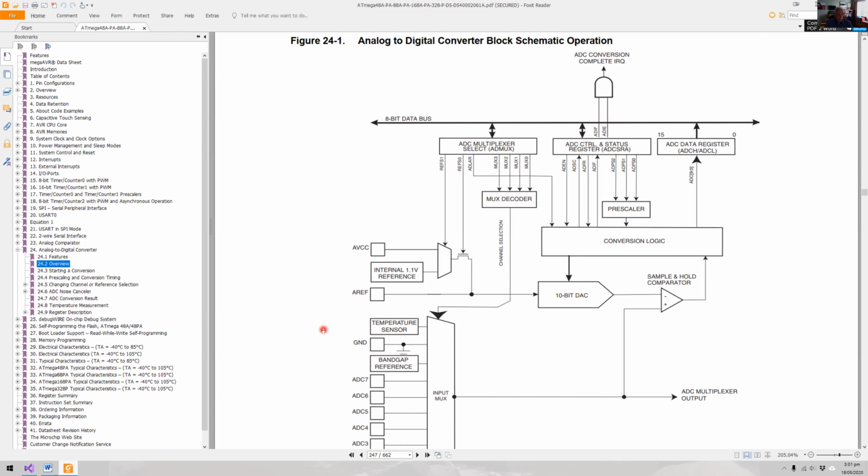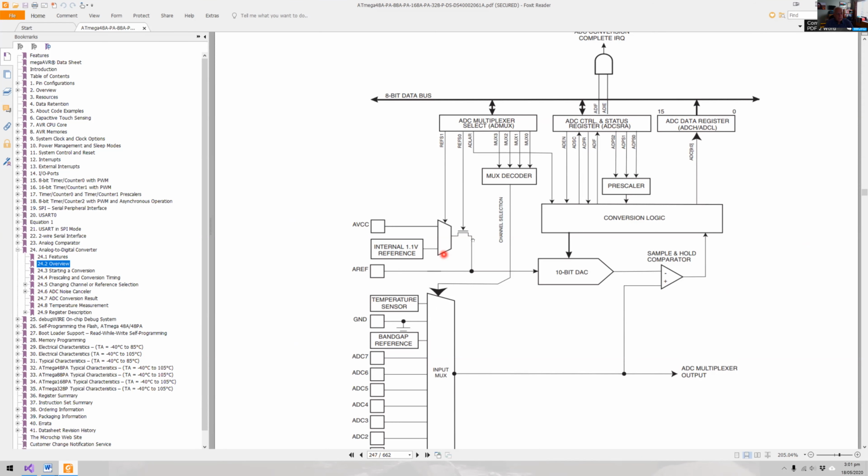Now this is the thing about a successive approximation ADC: it actually has a DAC inside it. What it does is convert the binary number to an analog voltage, compare that analog voltage to what is coming in, and then it does a bit of a counter thing here. I'm not going to go into this, but this is why you're seeing a DAC when we're actually talking about an ADC: it's the process of doing an analog to digital conversion using successive approximations.